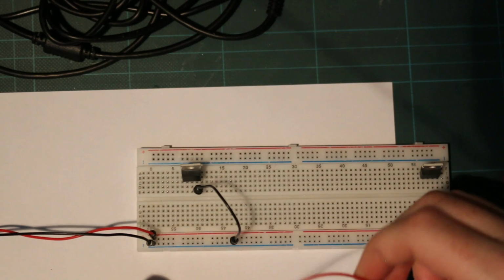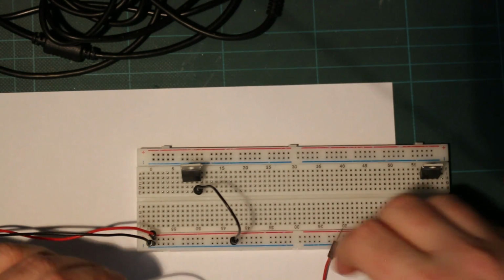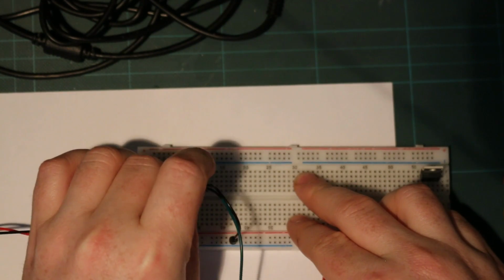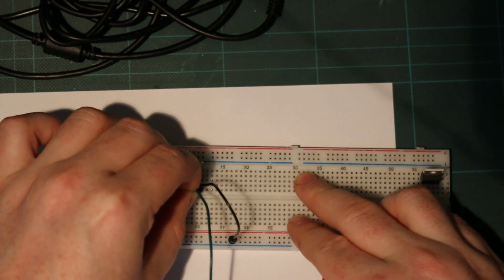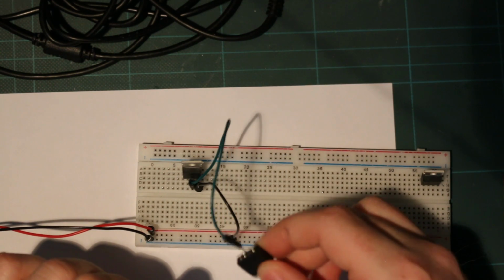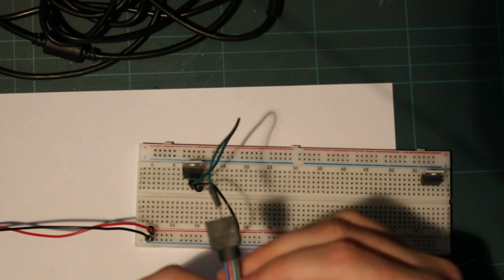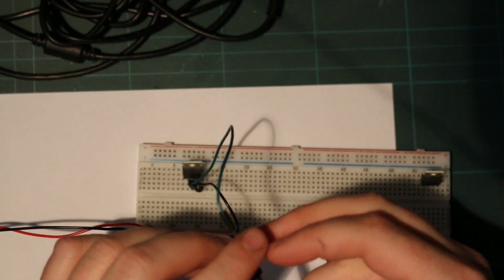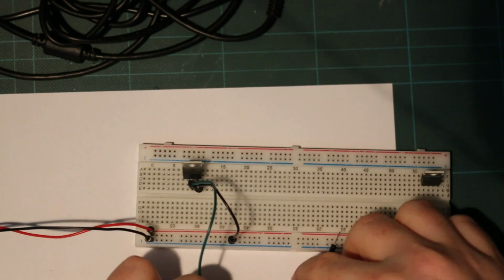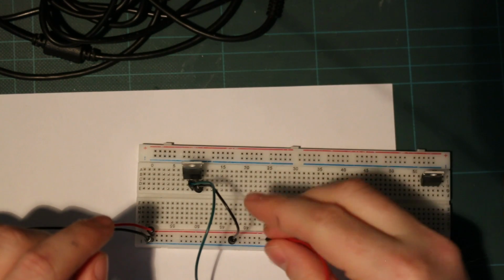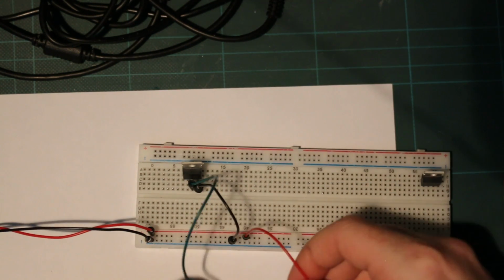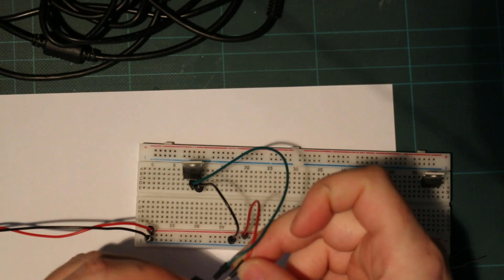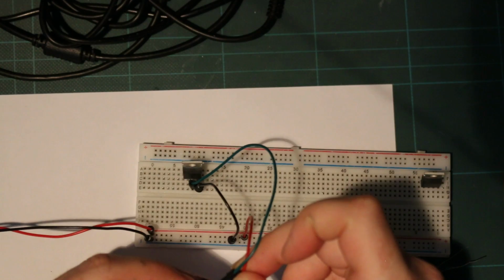Now, the output of this MOSFET is going to be this middle pin here. And if that would ever go in, perfect. And now I'm going to connect that to one of our 3 colored pins here. I have a green wire, so I'm going to connect it to the green output of this. Now the black pin here, I'm going to connect to the 12 volt of the LED strip here, as so.